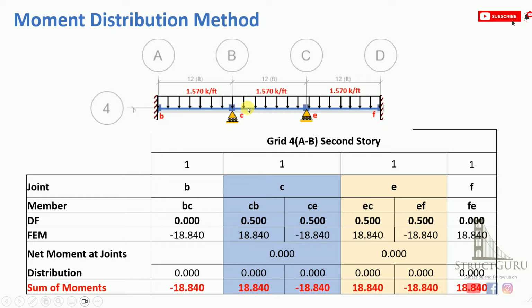But luckily, we have got symmetrical sections. All the loading magnitudes are same. So that is why we are getting the net moment as 0, because positive is to be generated from this side and negative is to be generated from the other side. So that's why the net moment is 0. So once you get the moment 0, if you apply the distribution it would also be 0.